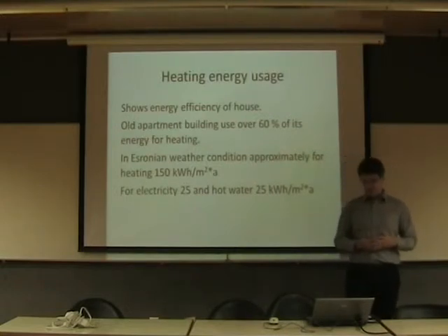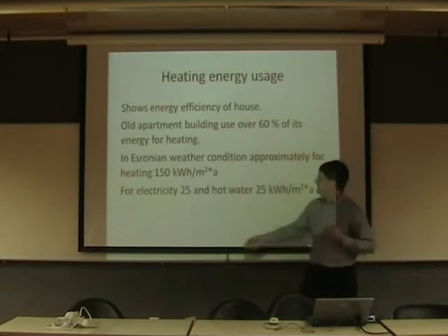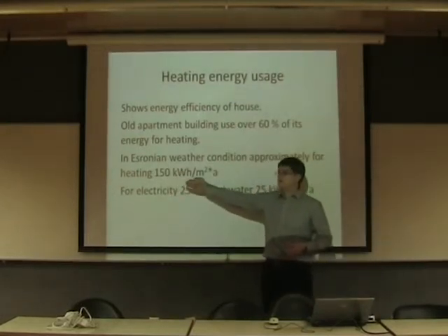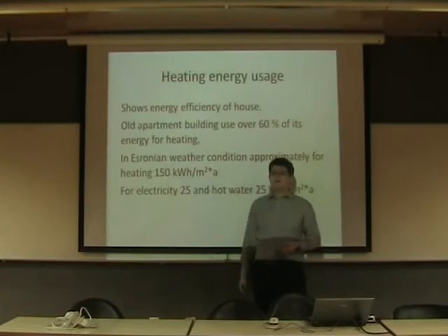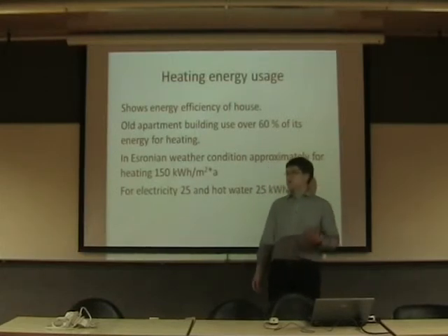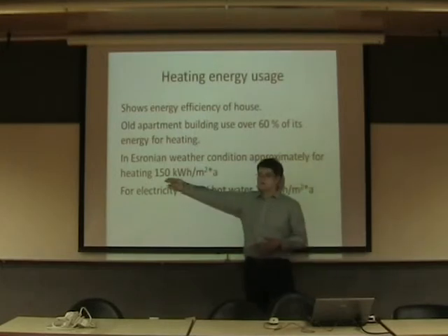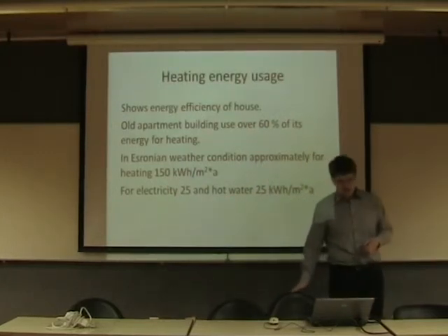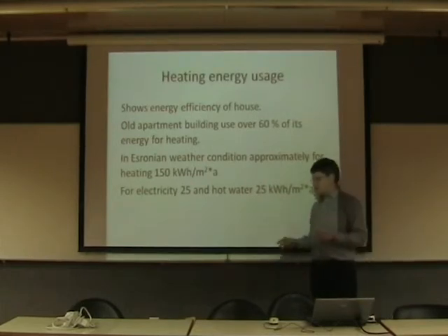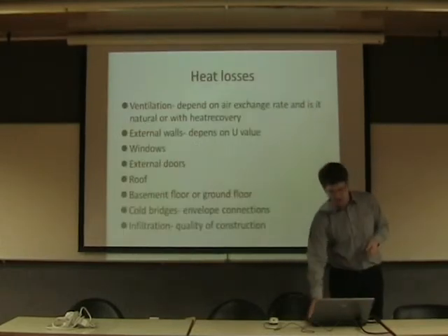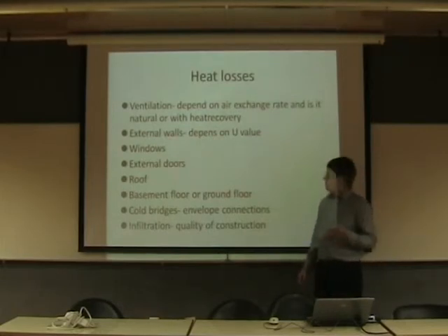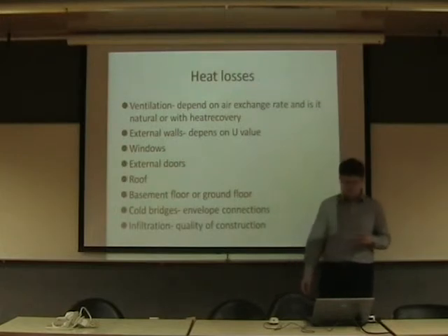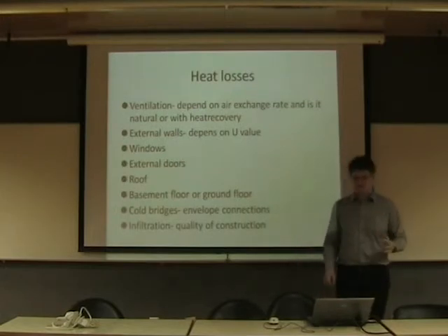But when we want to renovate them, then we want to have a number like 30 or 25, or whatever your case is. 2 days ago we discussed that for retrofitting houses it can be 25. Can it be achieved? It is a hard question, because we must think about where the house has its losses. We have energy losses from ventilation. This is one of the biggest parts, because we must change the air for a good indoor climate.